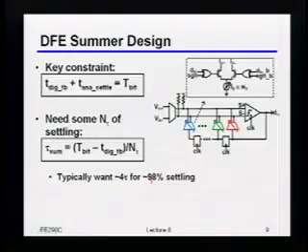Okay? So now, just to make sure that everybody gets why this is important here, let's say I was really talking about a 10 gigabit per second system. What does that mean the tau of this summation needs to be, approximately? What might be your digital feedback delay, roughly speaking, let's say in a 65 nanometer technology?